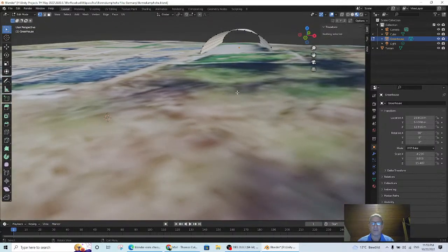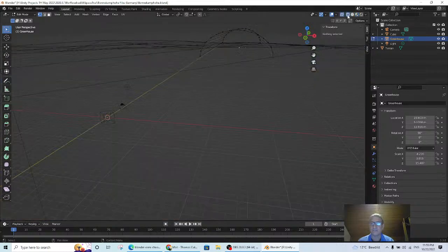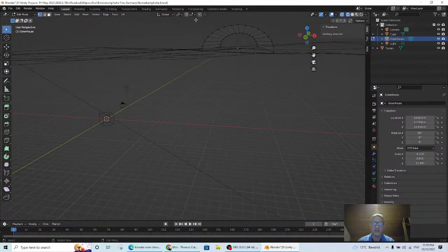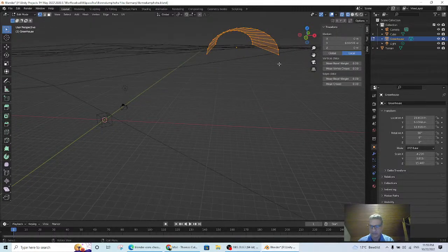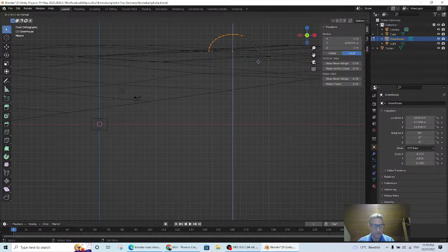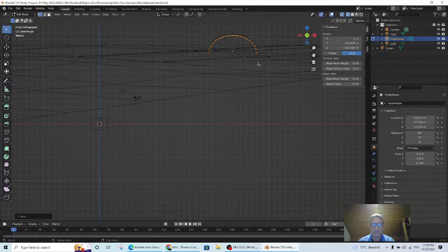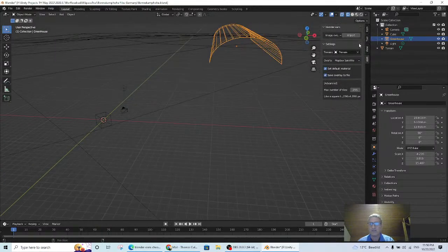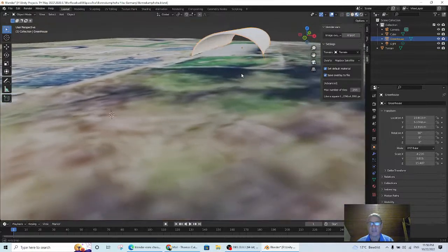And it probably is worth taking this and selecting all of it, and let me hit extrude in Z. Oops, that's not what I meant to do. Sorry, E for extrude and then Z, and then I want to actually grab it in Z and move it down to give it some thickness. All right. And then what I have is a much thicker thing, which is good. And then when I look at it on the terrain, yeah, I have what's the start of a greenhouse.